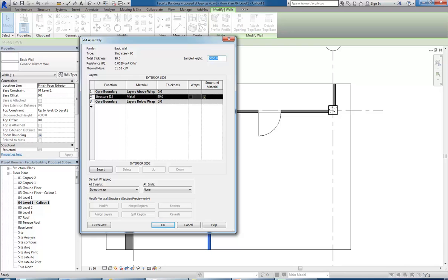So the technical terminology in Revit uses layers for the different elements in walls and floors, and then when you import things from AutoCAD, or if you are managing things in Revit the same way as you do in AutoCAD, the equivalent of AutoCAD layers is actually object styles, and I'll show you object styles in a moment. So that does come in handy with layers as well.